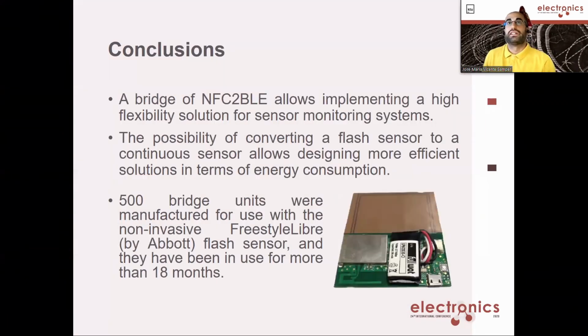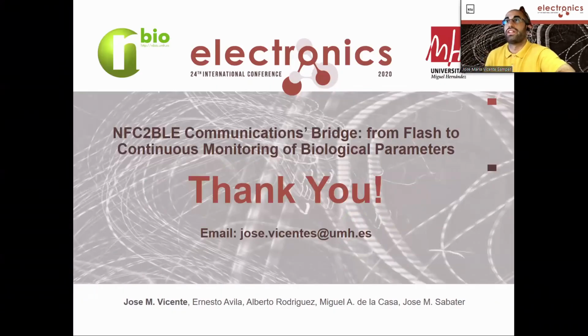Finally, as conclusions, a bridge of NFC to BLE allows implementing a high flexibility solution for sensor monitoring systems. Also, the possibility of converting a flash sensor to a continuous sensor allows designing more efficient solutions in terms of energy consumption. And 500 bridge units were manufactured for use with the non-invasive FreeStyle Libre, and they have been in use for more than 18 months with great results. Thank you for your attention.